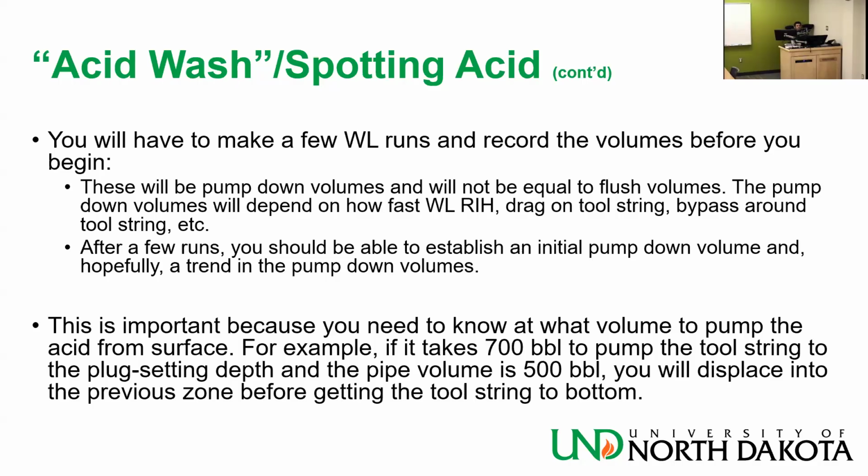This is important because you need to know at what volume to pump the acid from the surface. For example, if it takes 700 barrels to pump the tool string to the plug setting depth, and the pipe volume is 500, you will displace the previous zone before getting the tool string to the bottom.